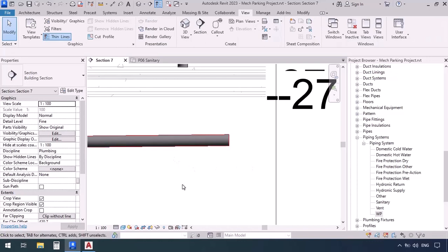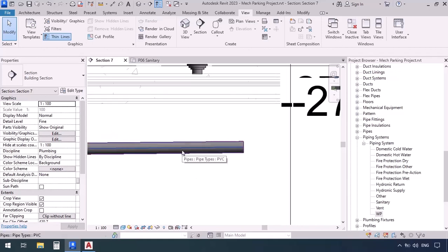So if you decide to drag to increase the length of a pipe, you'd have to make sure you don't change the slope because it's very sensitive. But if you go by right-clicking and draw pipe, and then try to draw a 45-degree angle, you would have to cancel it first and redraw. Now, to decrease the length, we can still drag, but on the condition of paying attention.